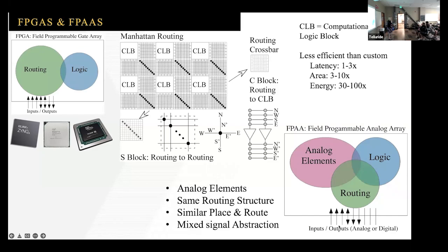It depends on the technology, and certainly we've built things bigger than that. But it's not just about building a crossbar. To build this infrastructure, each of these has its own different crossbar pieces. Making a bigger crossbar, I think Mike just set out crossbars at 100,000. The problem is not the crossbar, because the crossbar is tiny. Taking the data to the crossbar, you need cache memories. And in the area, a quarter is the crossbar, and the other 3/4 is the cache memory to feed the data to keep the crossbar going.